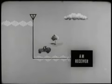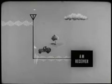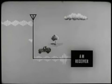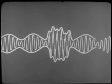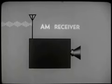But the lightning has added new variations. These are superimposed upon the variations carrying intelligence. There are many man-made devices and natural elements or occurrences that can affect the amplitude of the RF carrier. Each one adds more hash, more static, more interference. The receiving antenna will pick up both the composite RF waves from the transmitting antenna and the random noises generated by the lightning. These two will combine and distort the amplitude of our desired signal.